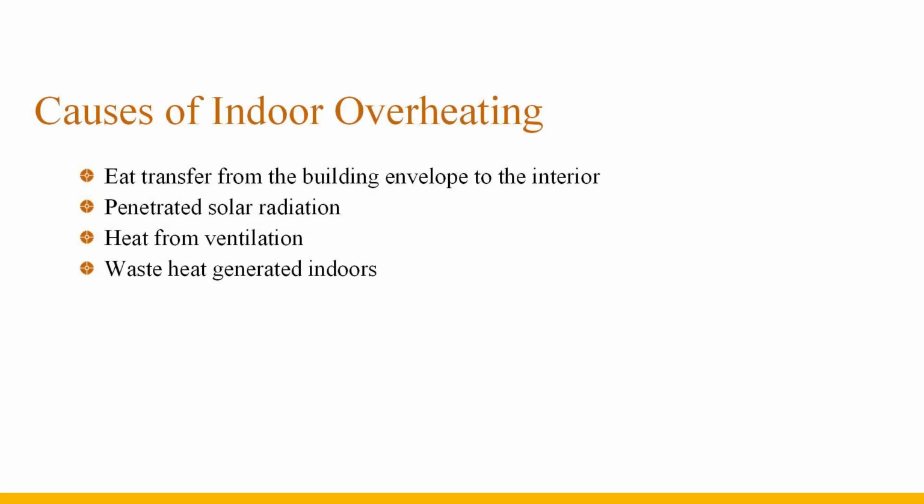There are 4 reasons for indoor overheating. The first is the heat transfer from the envelope to the interior. The second is the heat from the incoming solar radiation. The third is the heat brought in by ventilation. The fourth is the residual heat generated in the room.